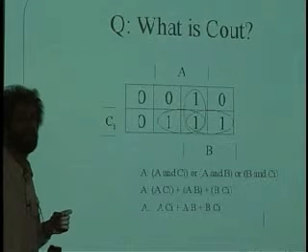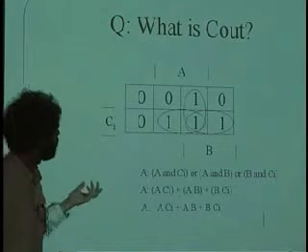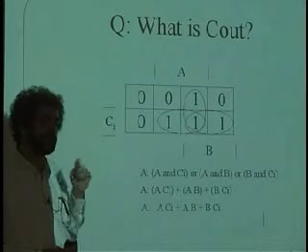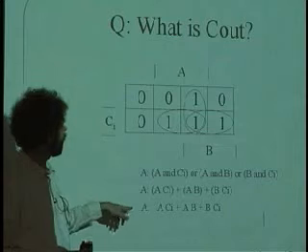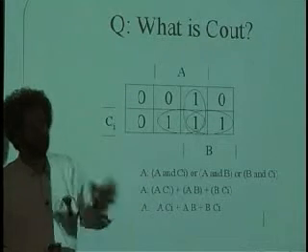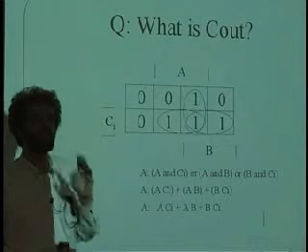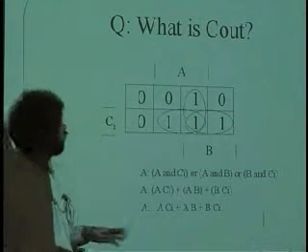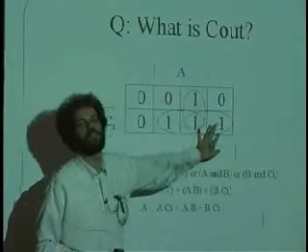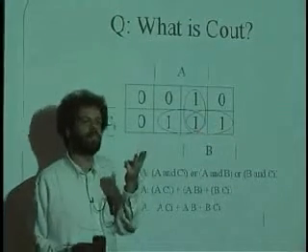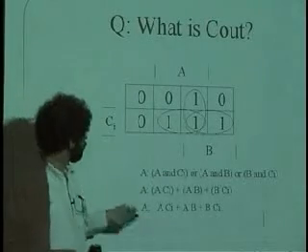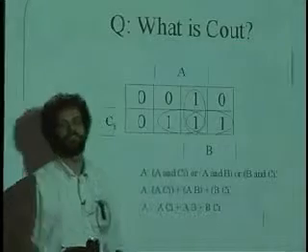Now you could do it, okay, but it would take a lot to finally see the symmetry and all of this stuff. And if you think about it a little bit more, what is the logic here actually saying? That at least two of these have to be 1. You got it. That two or more of the inputs need to be 1. And this tests for these two inputs, these test for the other two inputs, and these test for the other two inputs. You have 3 wires. There's 3 ways to test for 2 of them being 1. And so you just OR up those 3 cases.